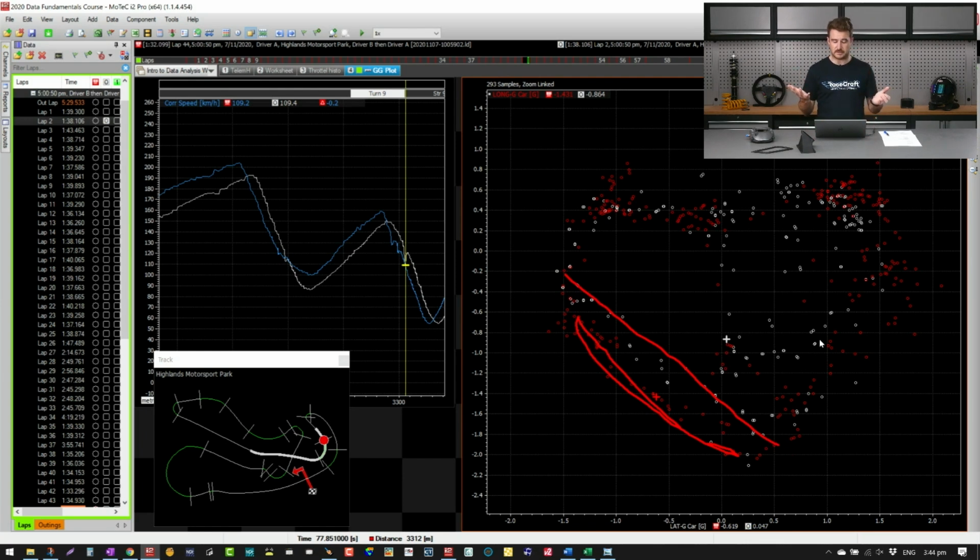those two driving styles. And in this particular case, this is going to be a big point of time loss between these two drivers. We've got one driver exploiting much more of the combined tyre load, where they're pushing right to the edge of both the longitudinal and the lateral components at the same time, as opposed to driving much more straight, turning and accelerating straighter, where you're not using as much of the combined force. That's really going to lose you quite a lot of time on track.